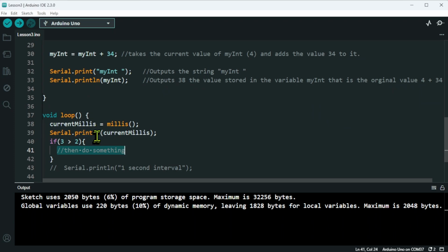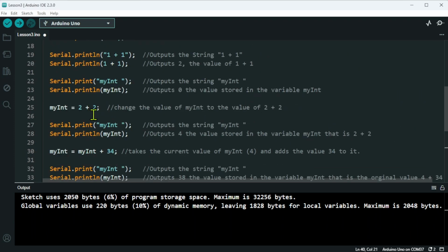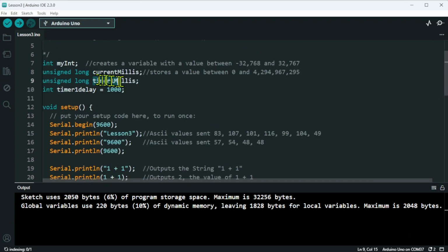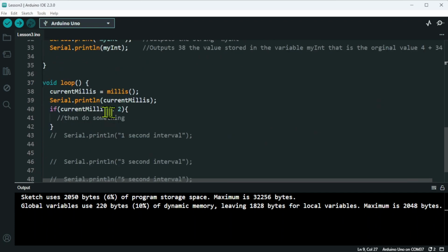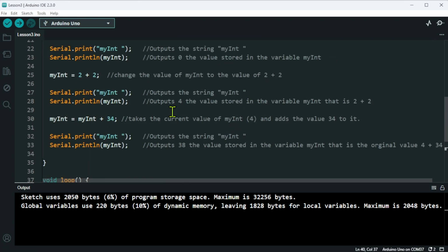constantly changing. So we're going to change this, and we're going to put in if current millis minus, and let's just get my spellings correct. We're going to take that variable down. So if current millis minus timer 1 millis is greater or equal, that is what that, if you like, that angle bracket followed by an equal.